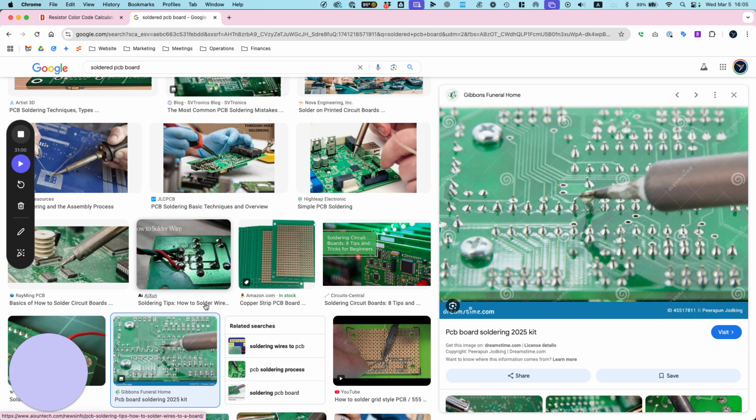Okay. Do it all again. When you're measuring voltage and resistance, you can just measure across two components. When you are doing current, you need to be in line. Think of it as a meter, just like a gas meter or electric meter. You have to be part of the system so it can count how much has flowed past it. So you actually need to break open the system and be in it for that to work.